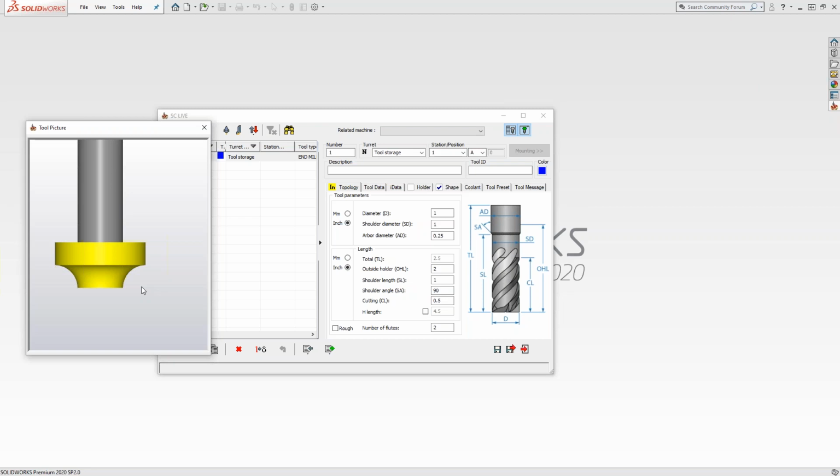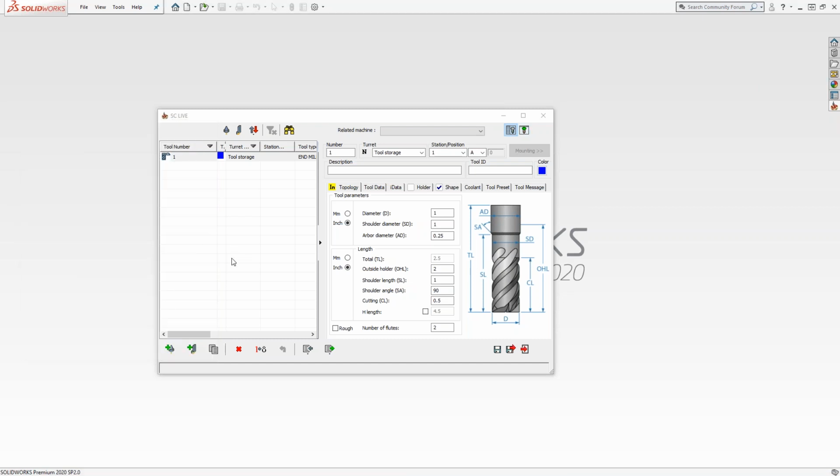So when you do any kind of profile tool path or anything like that using this tool, you're going to tell it to just shift a little bit upwards and maybe even inwards so that the imaginary point is in here and you actually form that shape there. Okay, so that is a very easy way to do your shape tool.